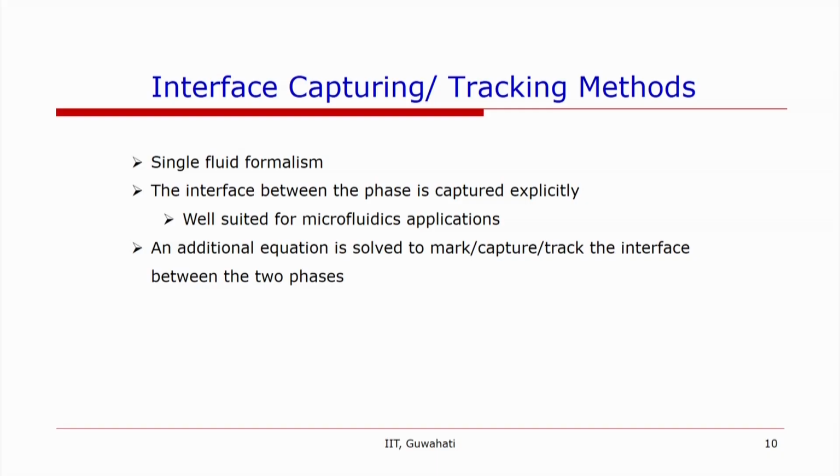So, for most cases in microfluidics, one does not use the Euler method, which is generally based on averaging of the equations. Rather, one uses interface capturing or interface tracking methods.